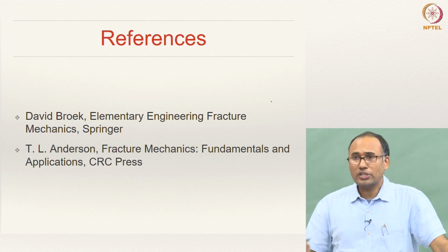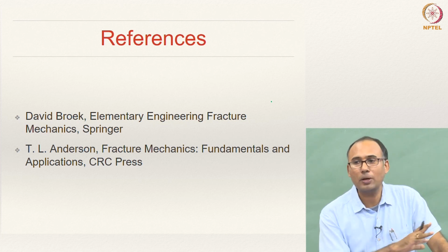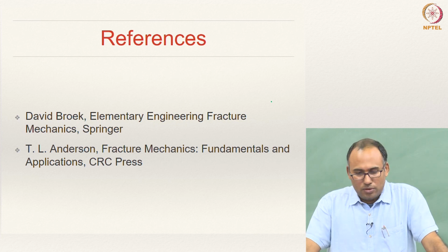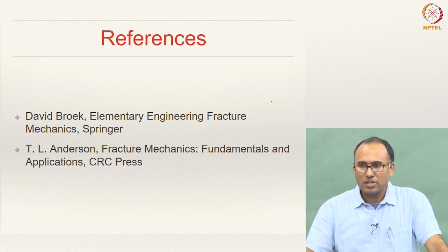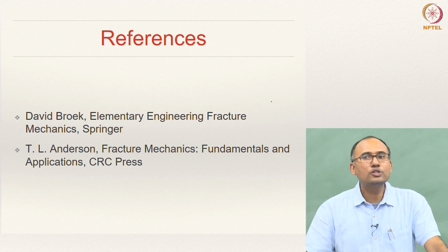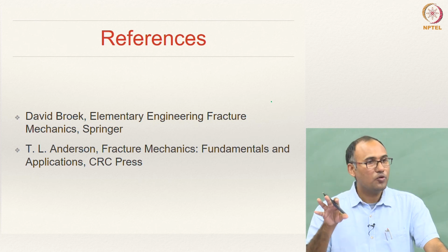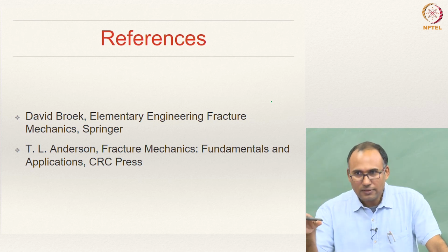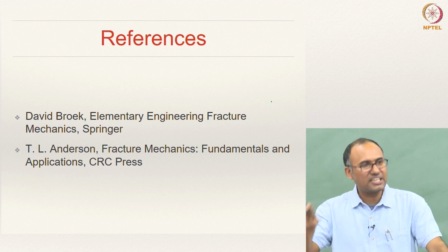All right. The purpose of this module on fracture mechanics is in no way to give you a complete understanding of fracture mechanics, but to educate you on the two concepts, the strain energy release rate and stress intensity factor, and to make sure that you understand that the crack propagates when the stress intensity factor exceeds the fracture toughness of the material, or the energy release rate exceeds the critical energy release rate.